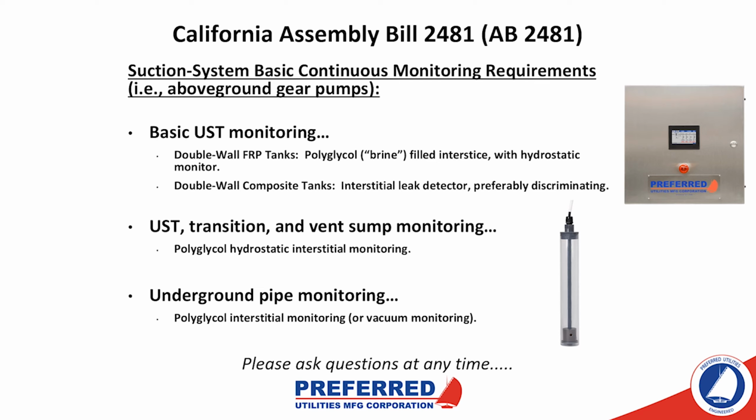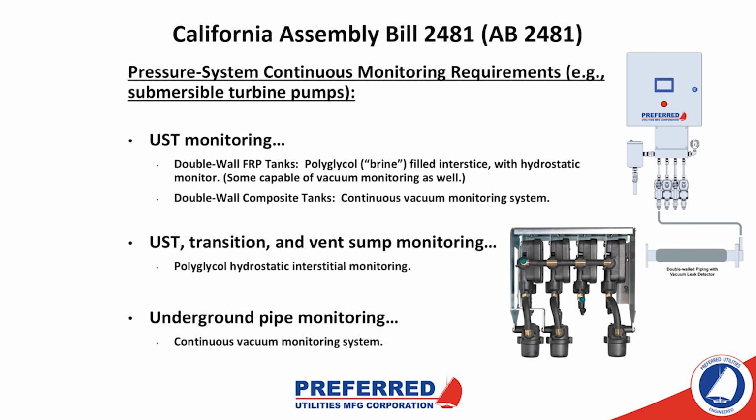As far as underground pipe monitoring goes, polyglycol interstitial monitoring is approved, or vacuum monitoring, even if you're not using a pressure system. So we need to make the distinction here that vacuum monitoring is required on pressurized UST systems. However, it's optional on a suction system.